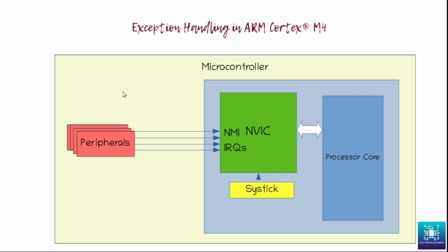So portability becomes easy. Any code you write on one microcontroller family, if you have actually ported a real-time kernel to one of these microcontrollers which utilizes a SysTick, that particular kernel would be more easily ported to another Cortex-M4 controller, because the SysTick is a generic timer which is inherent to the ARM Cortex architecture.